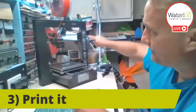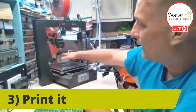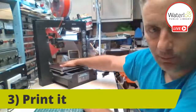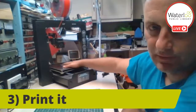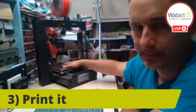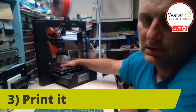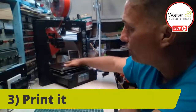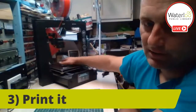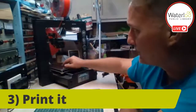It has this nice big box on top of another box on the bottom. We have a platform here. This platform, as I mentioned before, can heat up. You can specify in your slicer software, depending upon the material that you're using, what temperature to keep it at. For PLA, polylactic acid, it's about 60 degrees Celsius. So when you put in your SD card and you tell it to go print, it spends a little bit of time warming up, and this gets up to 60 degrees.